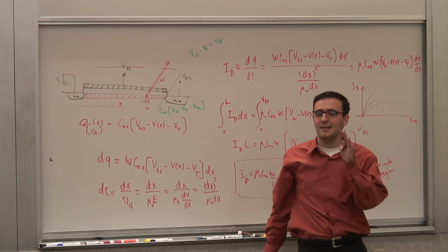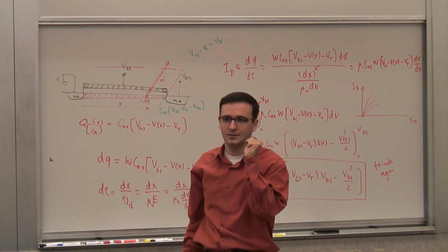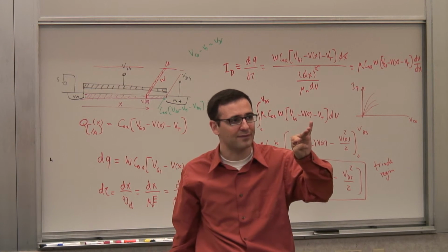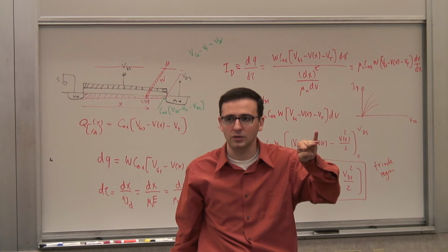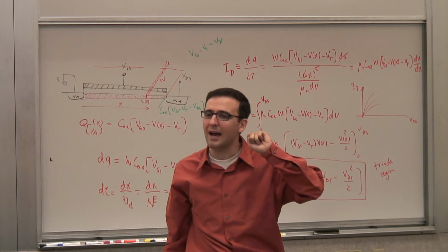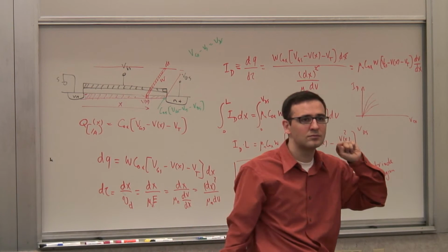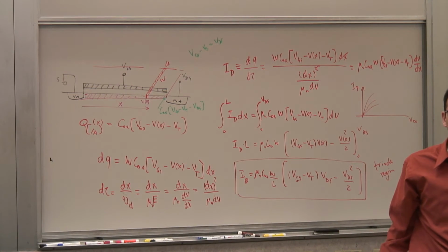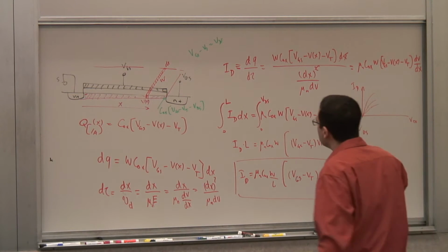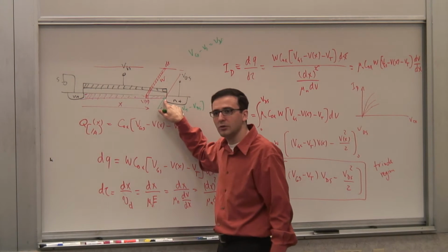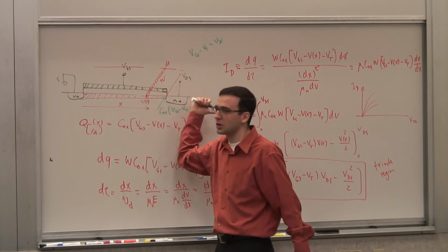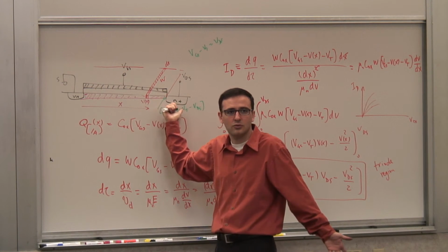So that's what we call the pinch off. The channel is pinched off at that point and beyond that point. But does that mean that we have to carry no current? No, right? It means the density of charge is 0 here. But the charges are flowing, the electrons are going this way anyway, and there's nothing to stop them.